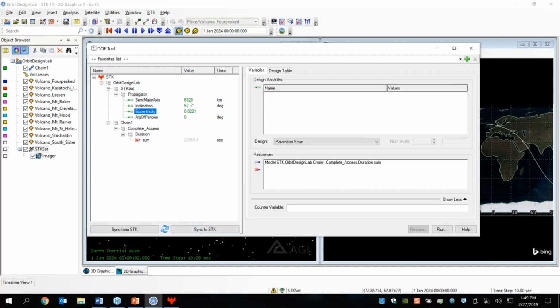And now we also want to update our semi-major axis. So recall that the one that we currently have written in there is one that we brought in for a circular orbit, but we used those as our perigee and apogee limits, so the boundaries that we had. So up at the top where it says semi-major axis, I'm going to write in 6,778, and the units are kilometers.